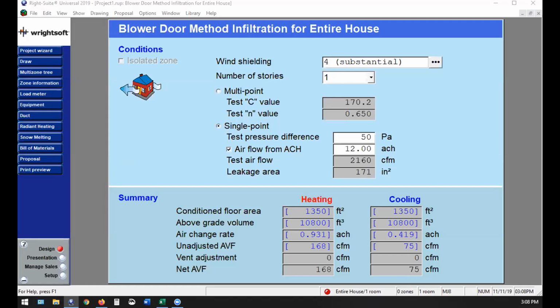So Matt, it really is 286. 288 is a common misconception. It's when you take 12,000 times 24, which is reverse engineering how many BTUs in a ton, which is why they come up with that. It's really close, but it is 286.